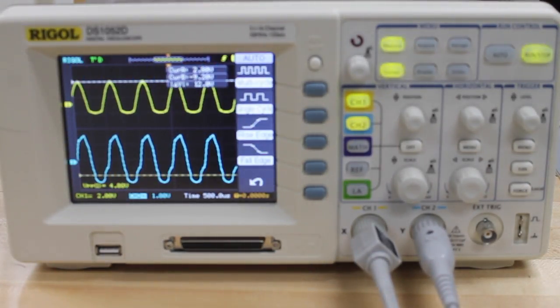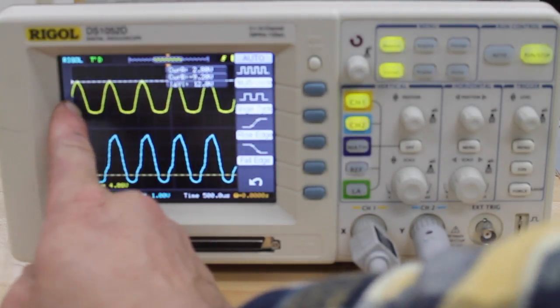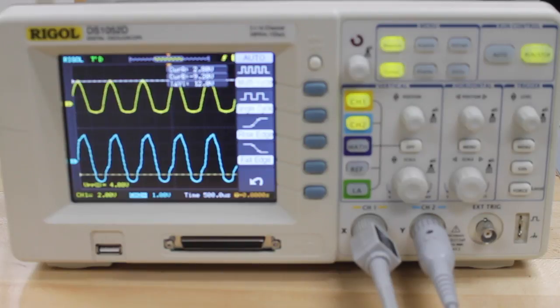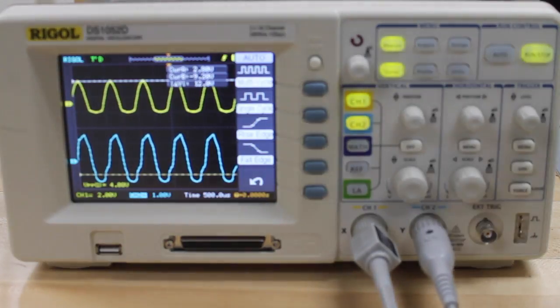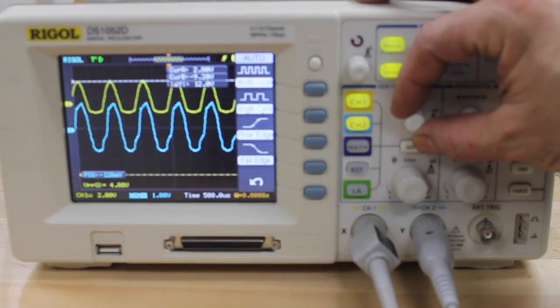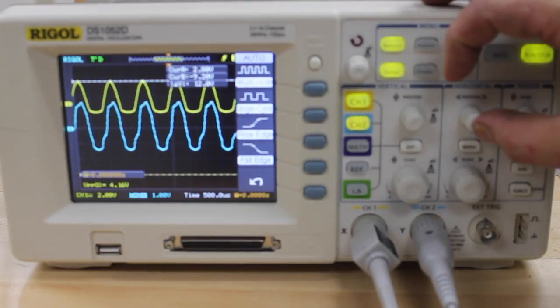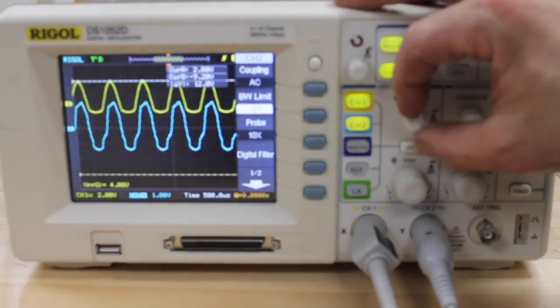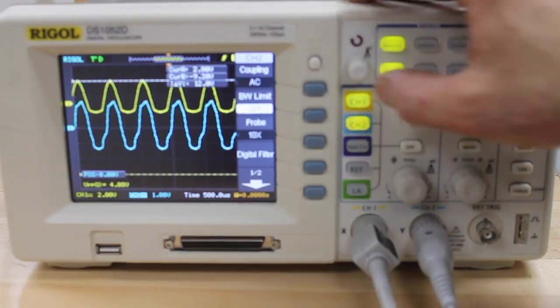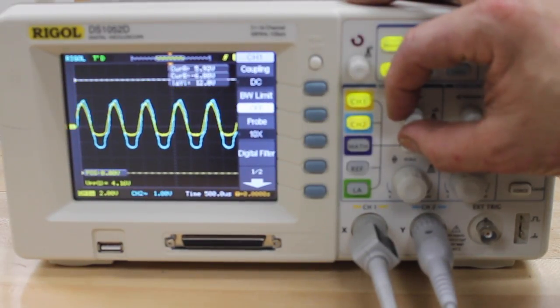As you can see, the wave being compared to the source is a little larger and a little distorted. We will shift both graphs horizontally to have the signals overlapping. I am shifting both of the signals vertically until they are on the x-axis. You can only move one graph at a time, so once you have moved one channel, you need to switch channels to move the other signal.